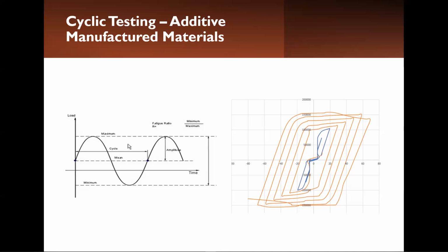As this is an additively manufactured material, there will be some kinematic hardening occurring that must be considered over the life of the material, and that can be shown on the right-hand side. So this one would be the broadening of the stress, and this would lead into some effects occurring in the fatigue life as compared to the regular sample.